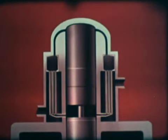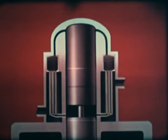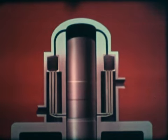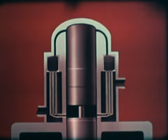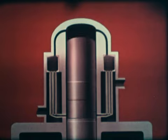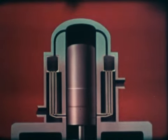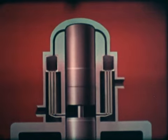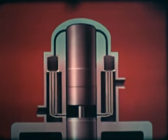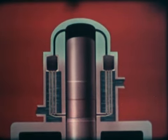The machine is driven by an electric motor in what we will call the forward direction. Again, expansion takes place in the head of the cylinder, compression at the base. In the expansion space, the gas will cool. In the compression space, heat does develop, only to be absorbed by cooling water. Thus, heat is transferred from the head to the cooling water.